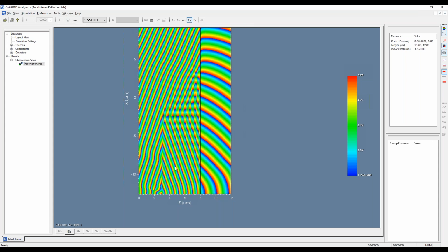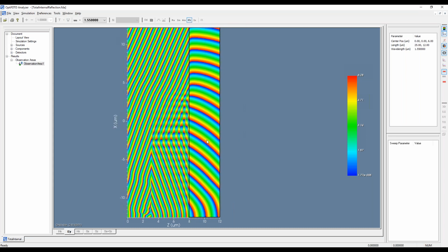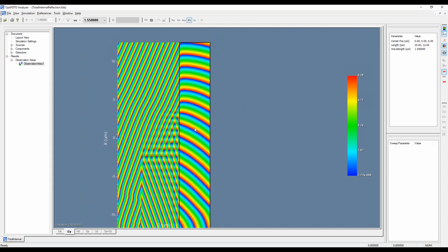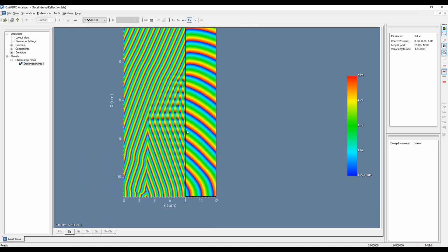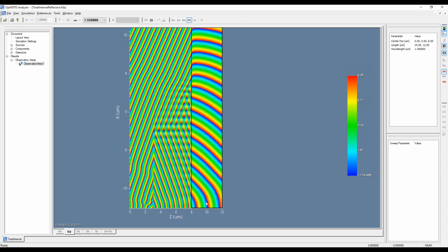We have this very straight phase or wave front, and it's decreasing linearly in the direction that we told it to, 20 degrees. And on the other side, we also get this nice, in certain areas, like I said, over here it's not so clear it's a plane wave, but in this area at least, it's got a nice straight front and it's decreasing linearly the phase. So we can say that's almost like a plane wave traveling from this boundary that way. But over here, of course, it's not so much a plane wave.